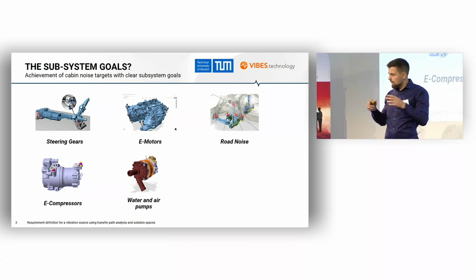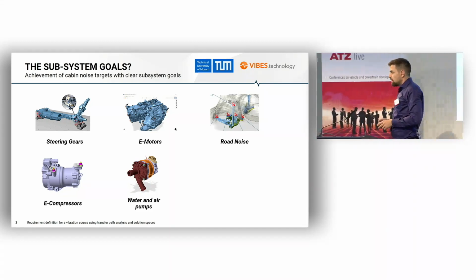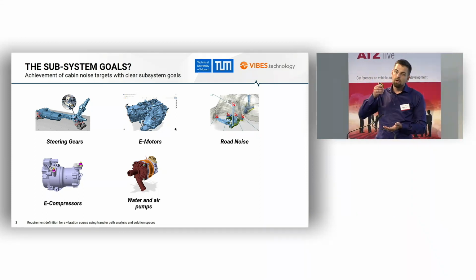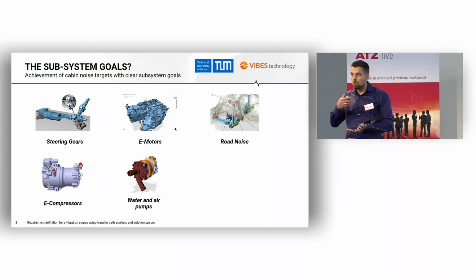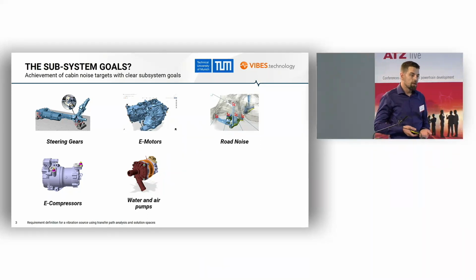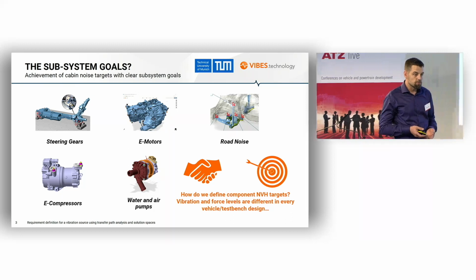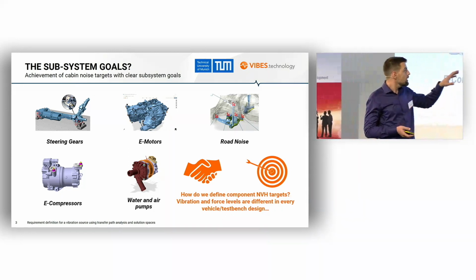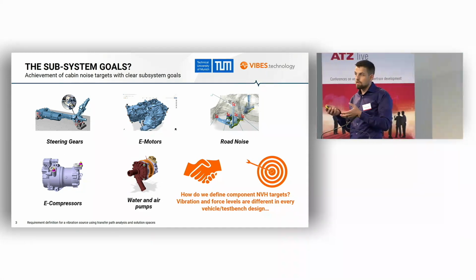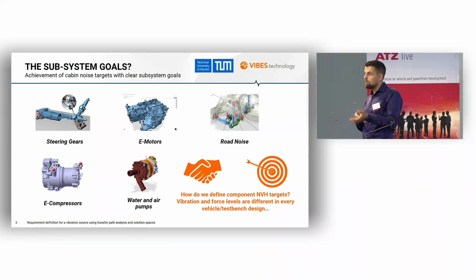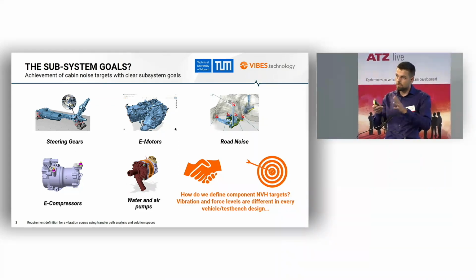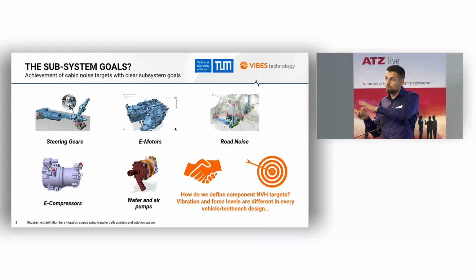And as you all know, at the beginning of a vehicle engineering project, you need to define component NVH targets, and you just don't know yet what the vehicle is going to be like. And to make matters worse, you have structural dynamics and physics, and we know that the vibration levels and the force levels that you could measure on a test bench or in a vehicle will all be very different, because the structural dynamic quantities are a property of the coupled system.